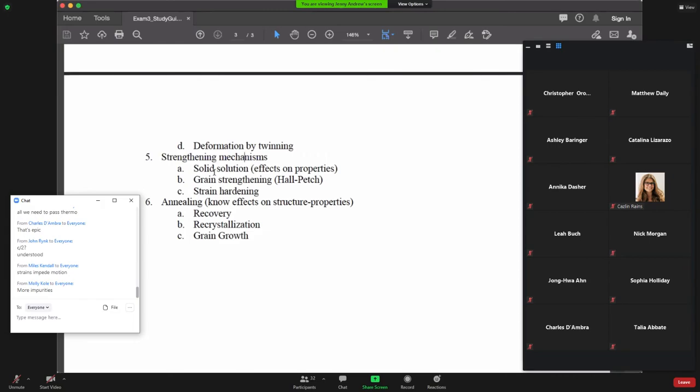So, in that open spot below the half plane of atoms in an edge dislocation, it's a little bit roomier. Those big atoms, the bigger solute, would fit quite nicely there. It relieves some of the strain energy in the system, and that makes it harder for the dislocation to move. And there are some images of this in the slides. So if it decreases the strain energy of a dislocation, then they're pretty content. They don't want to move.